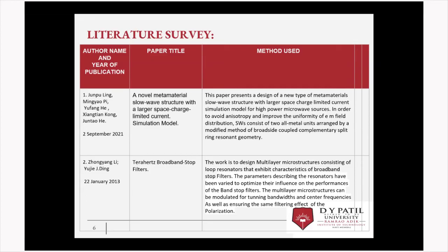After that, next is the terahertz bandstop filter. In this paper, I got the idea regarding a multi-layer microscopic structure consisting of loop resonators that exhibits the characteristic of a bandstop filter. The multi-layer microstructure can be modulated between two bandwidths, and it has a cutoff frequency as well as a center frequency, with the same filtering effect for polarization.